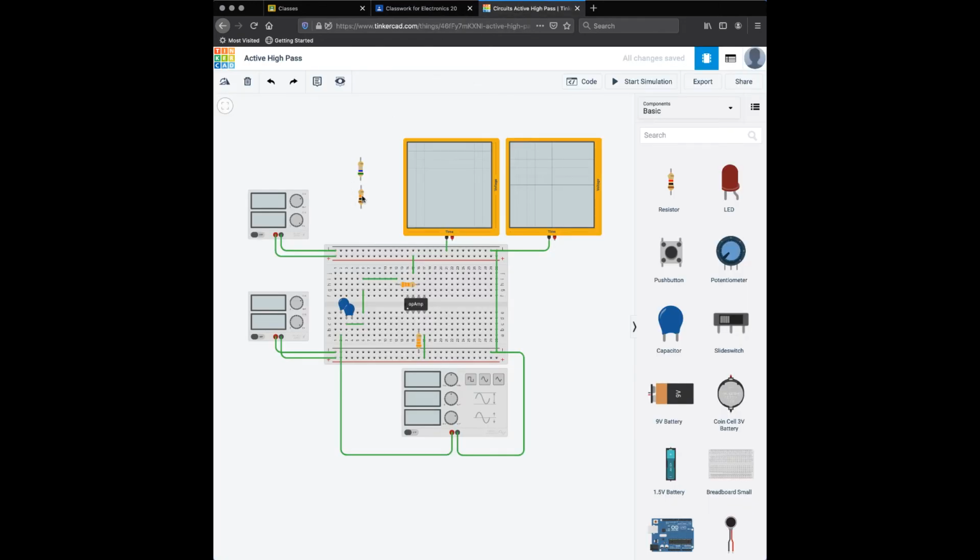I have a 10K resistor right here, and I'm going to take that 10K resistor to ground. I guess I'm going to do it right here. Maybe that makes sense. And then from the negative terminal on my op-amp, I'm going to go from the negative terminal right there to the top of that 10K. And so that'll get me to ground from there.